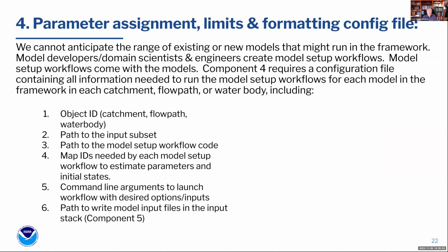Component 4 requires a configuration file containing all the information needed to run the model setup workflows for each model in the framework in each catchment, flow path, or water body, including catchment ID, path to the input subset, path to the model setup workflow code, map IDs needed by each model setup workflow to estimate parameters and/or initial states, command line arguments to launch the workflow with the desired options and inputs, and a path to write model output files to the input stack, which is component 5. I don't think that's an inclusive list, but I think it's a decent start of what we will need for that.